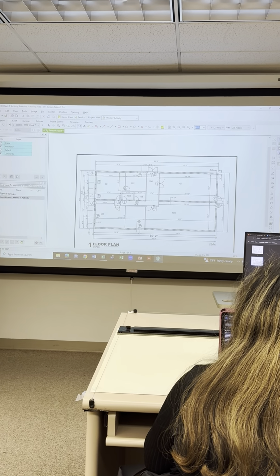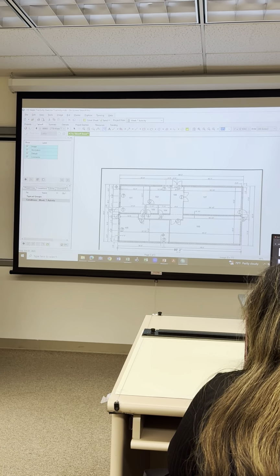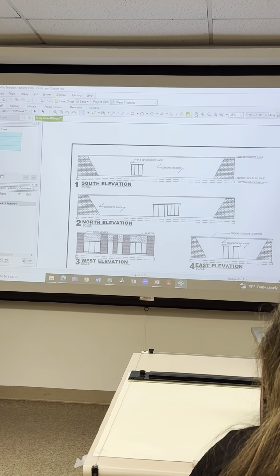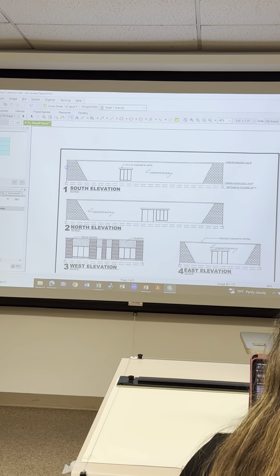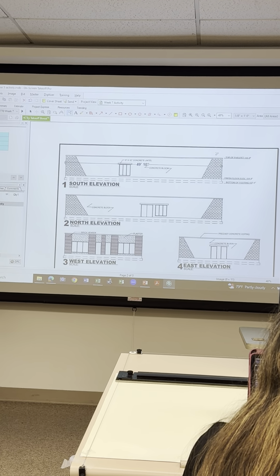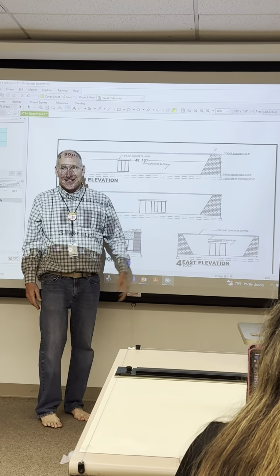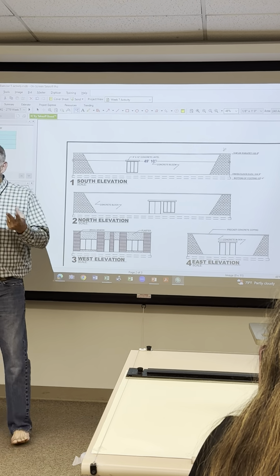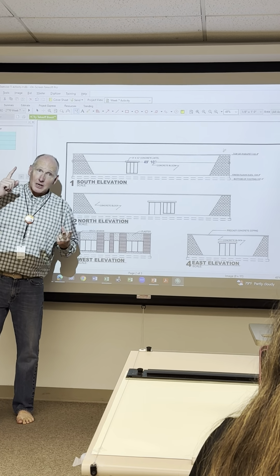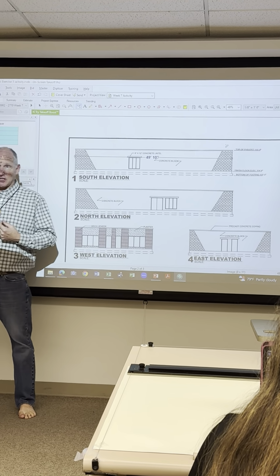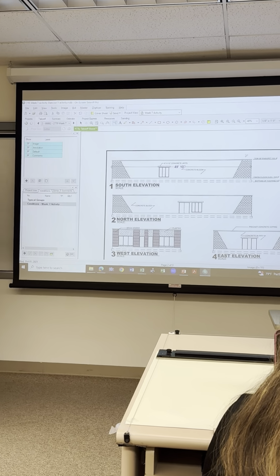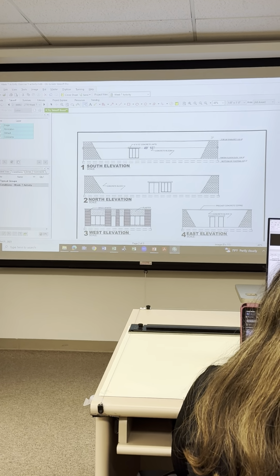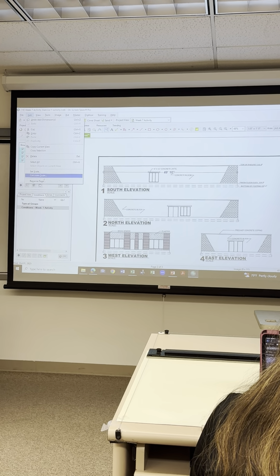Let's go to the other drawing though. If I go to my other drawing, and I see my elevations, I grab my scale, I know the south and north elevation is 80 feet. And I go, whoa, what happened? 4910. This is where I just check the scale, recalibrate the scale. If you have two sheets, two different scales, you calculate scale on each sheet. So instead of grabbing the scale on the other drawing page, we need to recalculate on our elevations by the same process. Edit, calculate scale.